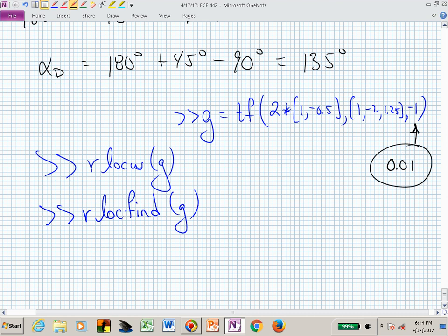So it will draw the same root locus, but now if you started to say something like grid, it would give you the wrong grid on your frequency domain plot. So now you kind of want MATLAB to know whether you're dealing with a continuous time or discrete time system. We'll pick up later on that.